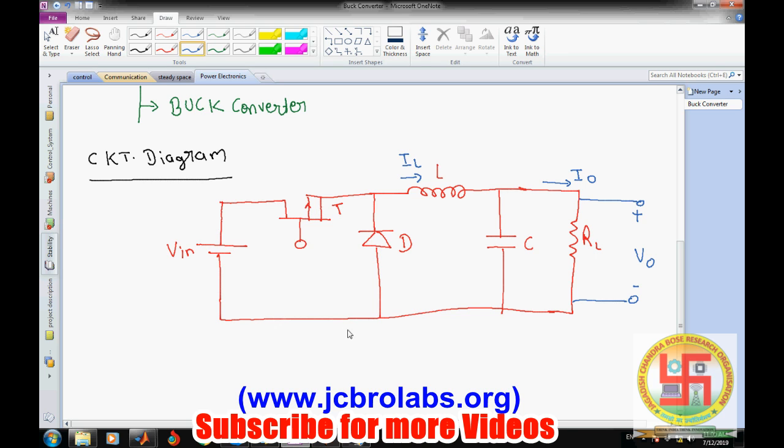What we do is simply apply a pulse train here, and the duty cycle of this pulse train keeps on changing, and depending on this duty cycle, the output voltage varies. When it is on, the transistor is on, so the input voltage is applied to the inductor, and the inductor gets charged up. And when it is off, this diode will turn on, and then the inductor will discharge through this one.